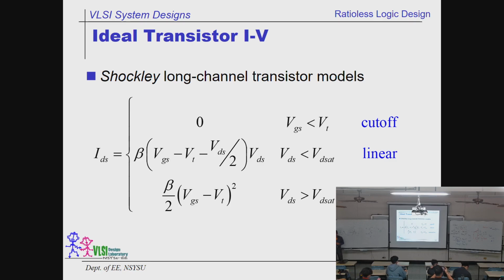And this is the equation that we learned before. It is called the first order long channel model. It's the same thing as the Shockley first order IV curve. The reason why I put it over here is that when I graduated in 1992, in the 1980s, Berkeley University in California developed the first version of the SPICE simulator.